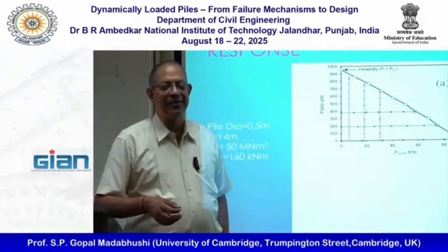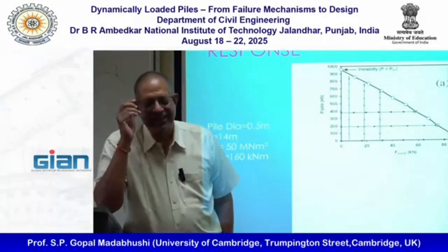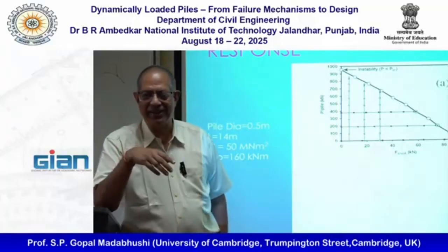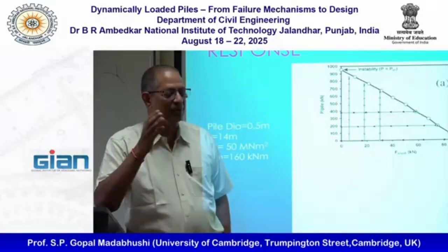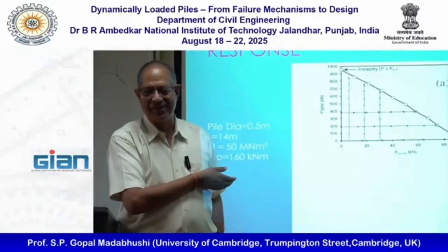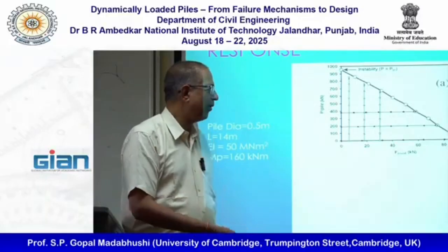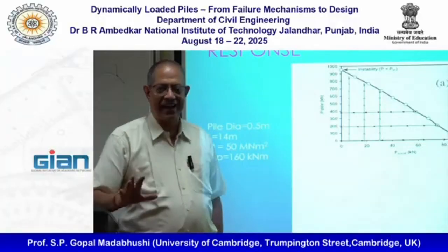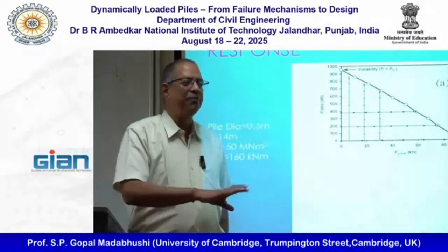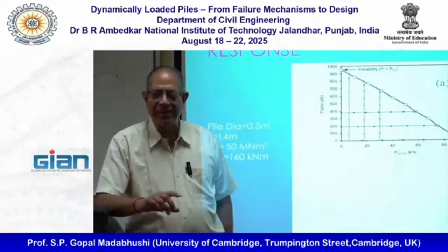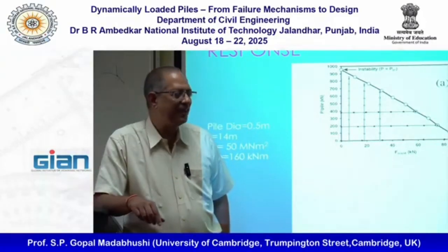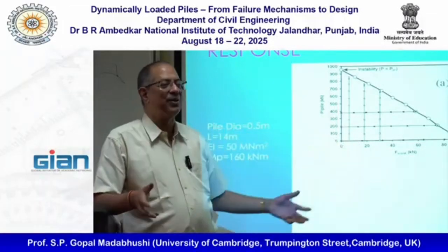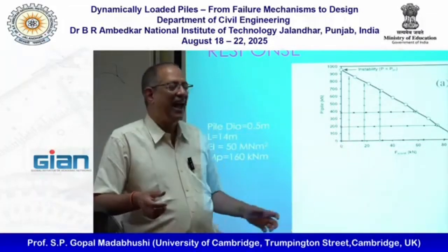But really, what frustrates me is that the same old things keep getting circulated. The Hamada equation of empirically calculating the movement, when we know the Newmark method works better. This is a complete process. We know the failure mechanisms, we know what the important factors are, and here is the data to support it. You can't ask for more than this.